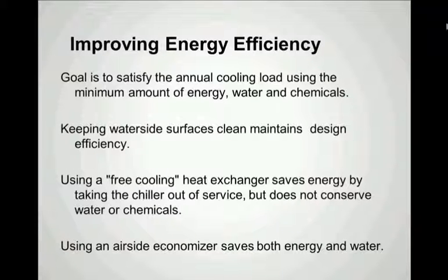So the goal then is to satisfy the annual cooling load, that area under the curve, using the minimum amount of energy, minimum water, and minimum chemicals. And we can do that using some very basic strategies. One is to keep the waterside surfaces clean, as well as keeping the cooling tower clean, so that we can achieve our design efficiency in terms of heat removal, not only in the chiller but at the cooling tower.